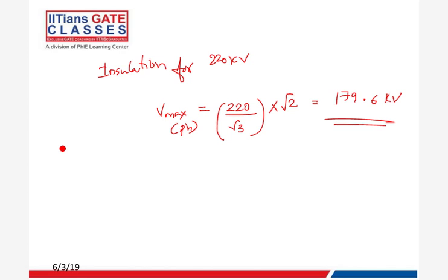Right. And again, you have seen the porcelain insulators, right? There are disc type insulators. We will look at what the different types of insulation are. One rule of thumb is that one disc corresponds to 11 kV, right? So next time when you look at a transmission line, just by counting the number of discs, you can determine what the voltage level is. This is just a rule of thumb, for your information, right? So this is about insulation.